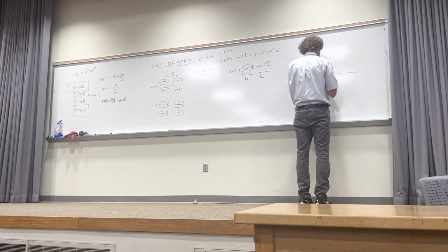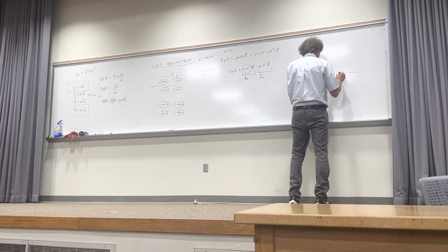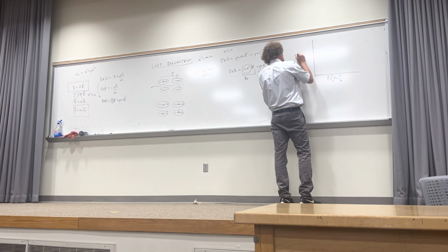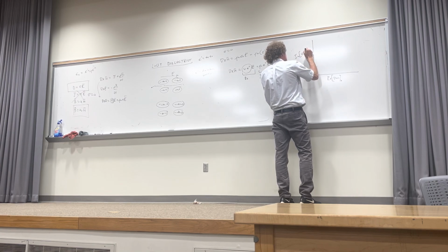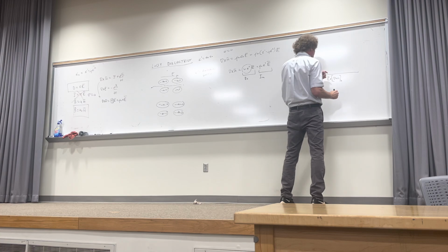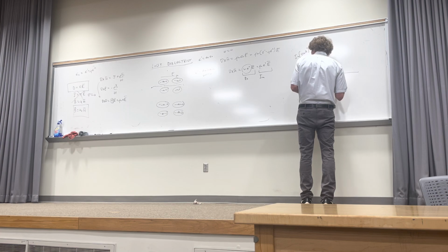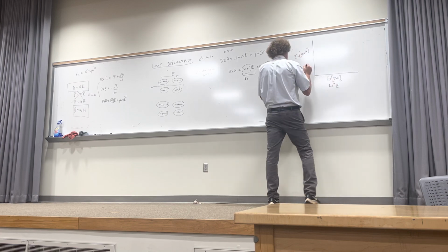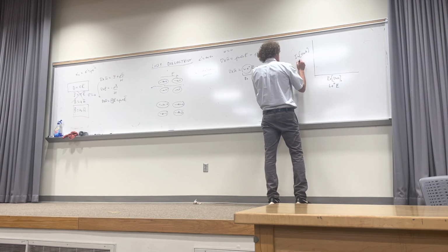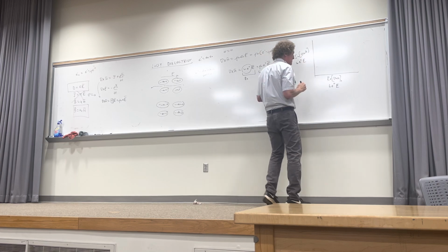They'll have a plot of the real part of curl of H here, and then they'll have the imaginary part of curl of H here. Well, the real part of curl of H is just omega epsilon double prime E, and the imaginary part of curl of H is going to be just omega epsilon prime times E. Now, can you all follow me?